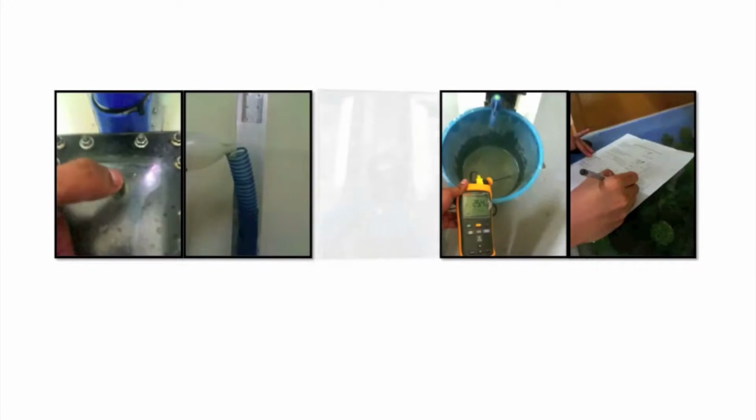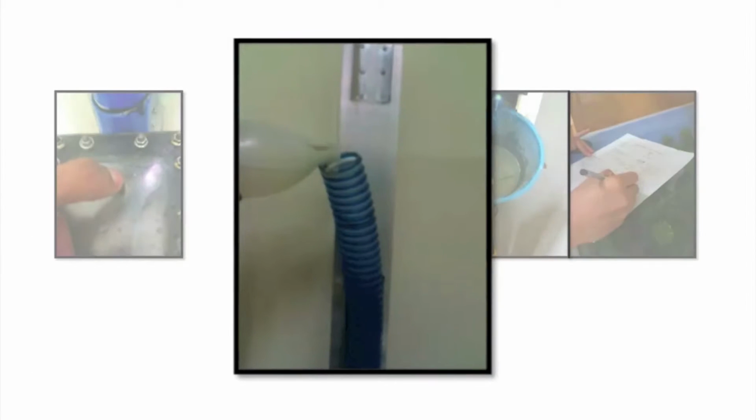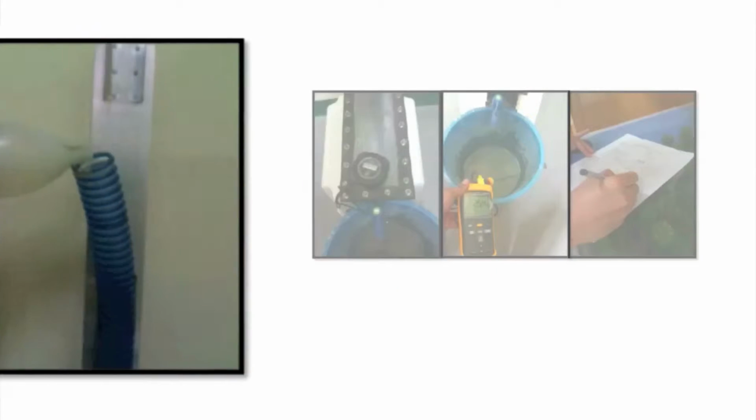Then weigh the mass of the saturated soil. Leave it for 24 hours to fully saturate. Now, the sample is ready to be tested. First, remove air voids using the tap. Then fill the pipe at its corresponding hydraulic gradient.